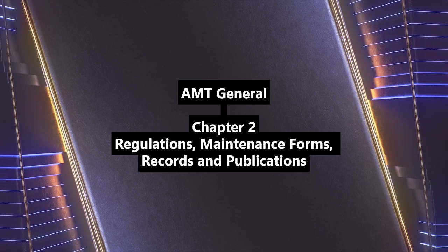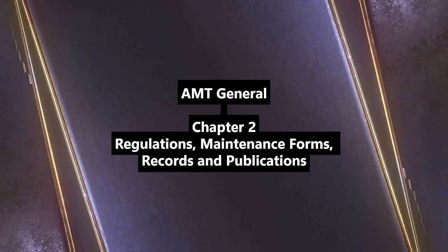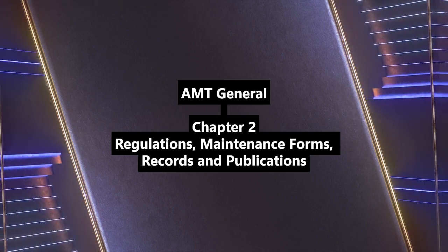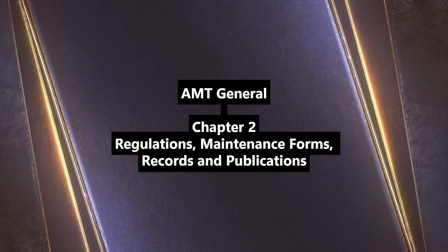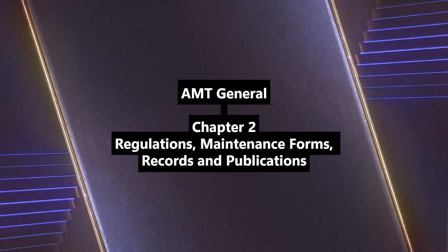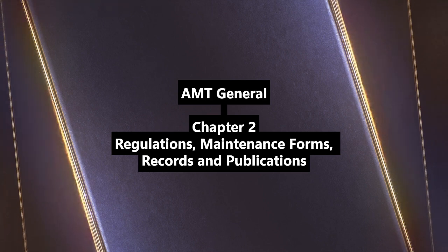And Part 135? 14 CFR Part 135 handles operating requirements: commuter and on-demand operations. Think shorter distance scheduled commuters and unscheduled on-demand, like air taxis or charters. Okay, smaller commercial operations. Key requirements? An operations manual is crucial, and Section 135.411 is big for maintenance.